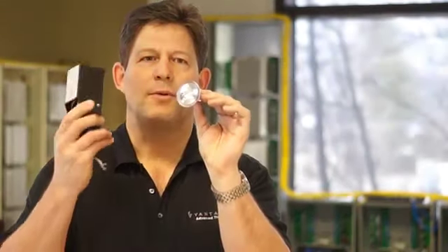When the lamp is low voltage, and a transformer is used to convert the line voltage to 12 volts, for example, to apply to that lamp, then in addition to the lamp itself, some complexity is introduced by the transformer. Now, conventional wire-wound or magnetic transformers are compatible with this type of dimming, or forward phase dimming, so long as certain factors are implemented in the dimmer.